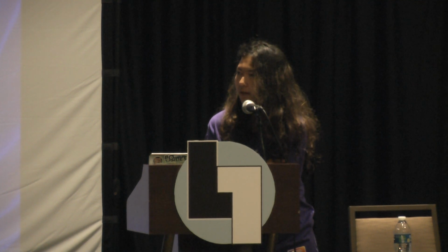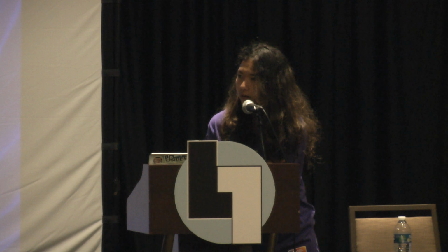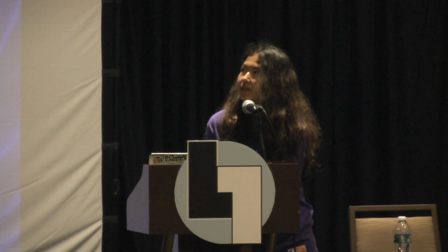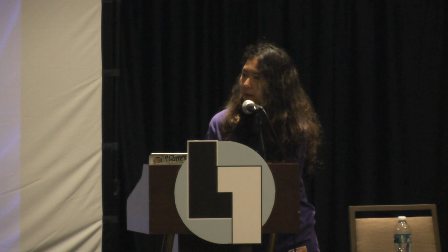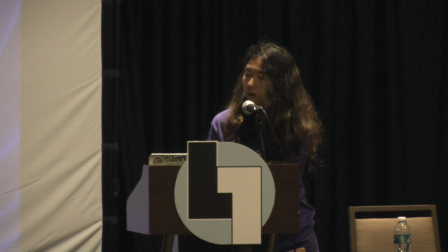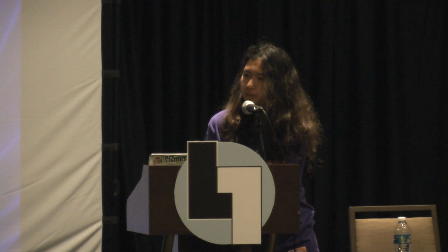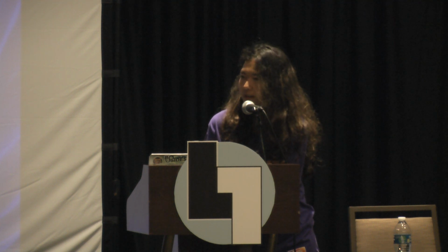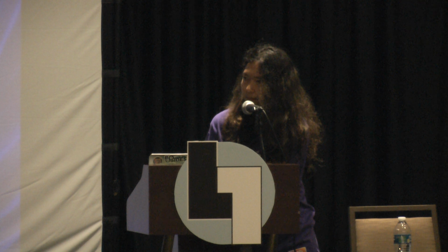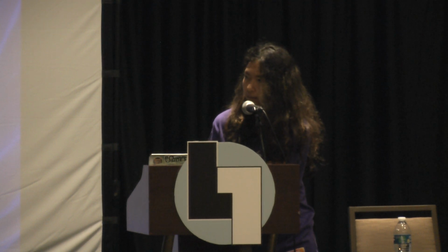Oh, antennas, yeah. Yagi antennas, if you're trying to get reconnaissance on weather imagery satellites. You can use turnstile antennas, or helical antennas if you want a more omnidirectional approach. I would say either get a standard Yagi that operates in the 400 megahertz range for weather satellites.